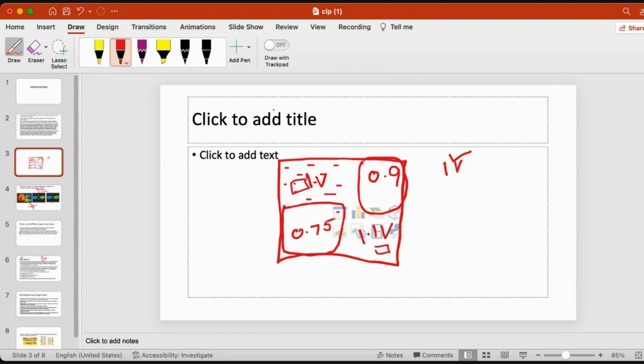So how to add an ESD cell? Whatever the operating voltage, if this cell is working for VDD1, and this is VDD2, VDD3, then you have to connect these ESD cells to VDD1 and the ground. So this is about ESD.